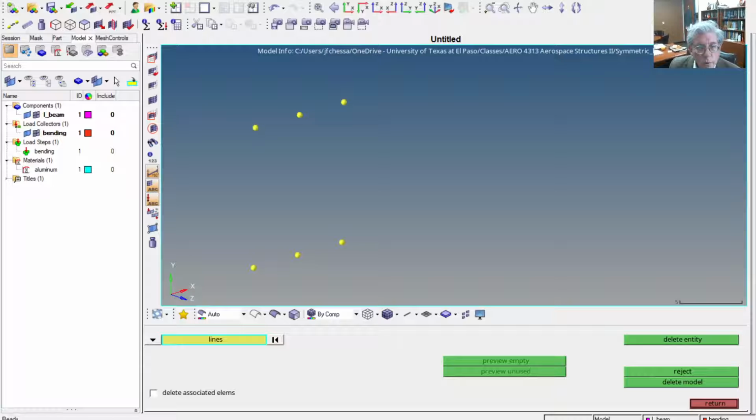So what we're going to do is create a shell element mesh and then apply SPC boundary conditions. But we will also create an RBE3 element, which is like a rigid element that's going to allow me to correctly transmit the point bending moments that we're using onto the whole face of the I-beam. It'll make more sense when I start to do it, okay?